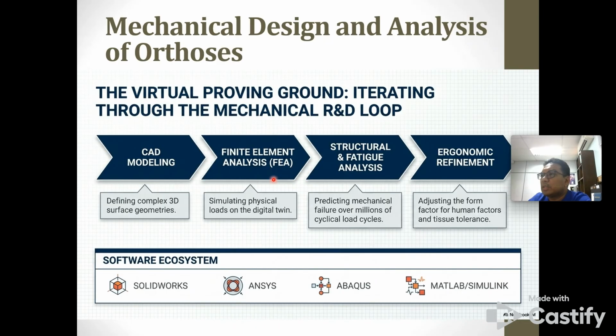And then you can do finite element analysis to simulate the stress and force during contact using ANSYS software. There is a more advanced option if you use Abaqus. Basically, we have all these four software in our school to do a complete study of the design of the orthosis device. Then you can study the structural and fatigue analysis using Abaqus, so you can predict the mechanical failure over the cycles, how much your orthosis device can sustain.